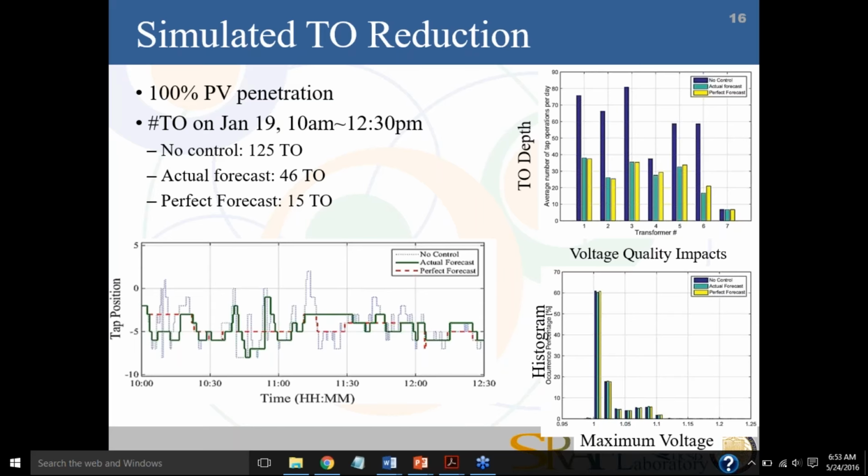And so we're currently working on techniques that detect that the voltage is very high. We would actually then operate the tap, even though it was recommended to remove that operation, because we do want to maintain the required voltage.